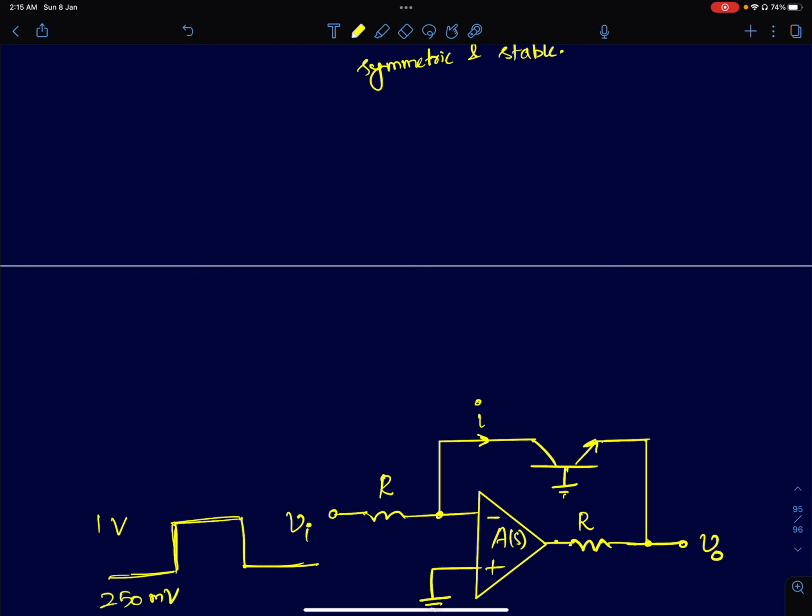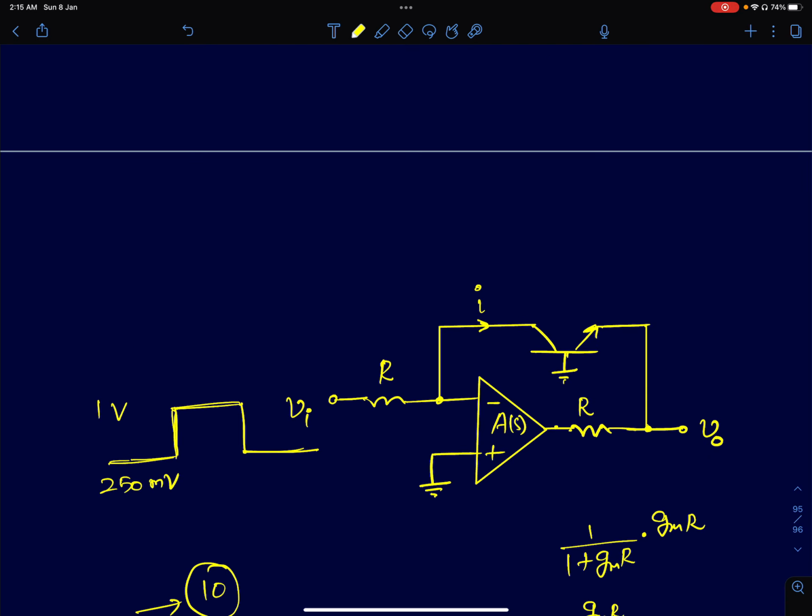So to do that, what we can do here is just add a resistor before this amplifier. Now remember, you need the logarithmic amplification, so I need to reduce the loop gain. To reduce the loop gain without impacting this, say I need this function, minus Vt ln of Vi upon Is times R. I need this function. So I can't put a resistor anywhere in this path. If I reduce this resistor, then I'm going to affect this transfer function. I don't want to do that.